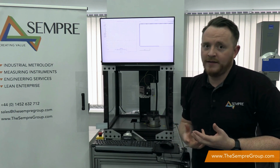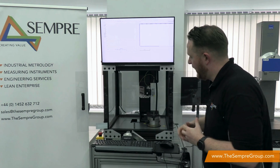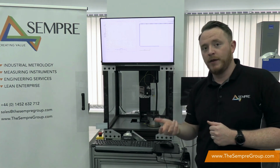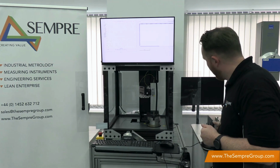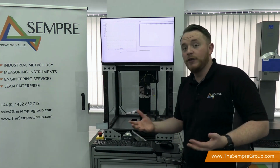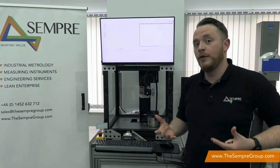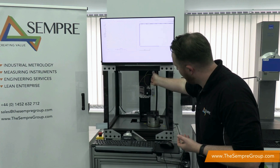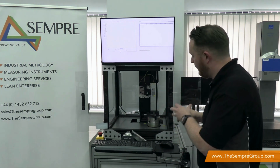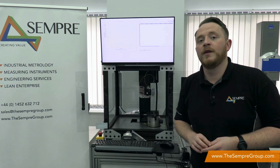Novacam also supply a system called a tube inspect, which is what we have here, and we've also got the bore inspect. The principle of how the bore inspect works is that the probe will rotate as opposed to the component. In the example we have here, where I rotate the chuck, the component is moving. Sometimes you might have a 60, 70, 150 kilogram component. We don't want to be spinning that on a chuck. It gets very expensive when you start to try and load components that heavy. So what we want to do is bring the probe in on an axis, and we can rotate the end of the probe. So don't be put off by potentially seeing very small components. If you've got larger components, we can still look to create your measurements on those samples.